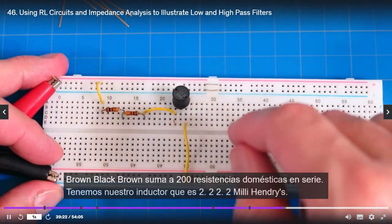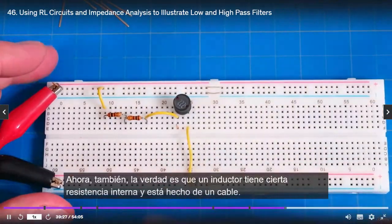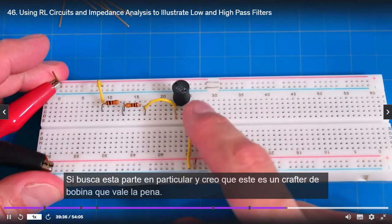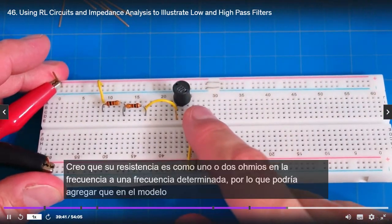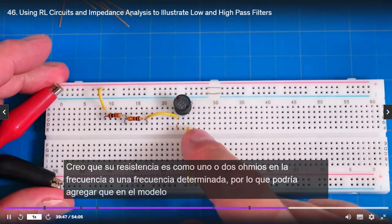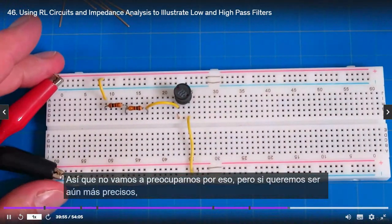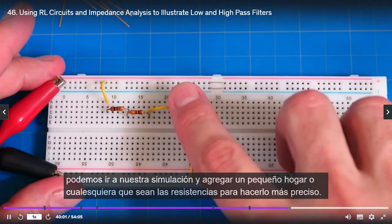We got our inductor, which is 2.2 millihenries. Now also, truthfully, remember an inductor has some internal resistance. It's made out of a piece of wire. Remember its model is an ideal inductor and a little resistor. If you look up this particular part, I think it's either Coilcraft or Würth, its resistance is like 1 or 2 ohms at a certain frequency. So you could add that to the model to be a little more accurate, but it's going to be a 1% difference compared to our little resistors here, so we're not going to worry about it. But if we want to be even more accurate, we could go to our simulation and add a little 1 ohm, or whatever the resistance is, to make that more accurate.